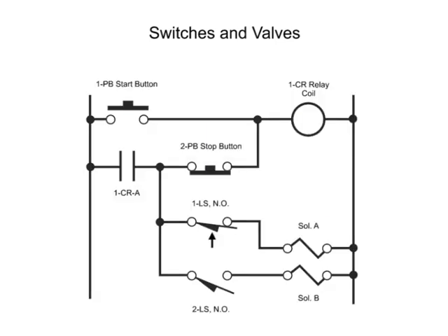For example, consider the limit switch, which is an electrical switch operated by the motion of a machine or presence of an object. In this circuit, there are two limit switches. Limit switch 1LS is a normally open switch. The arrow shown next to the switch indicates that the limit switch is normally opened, but is held closed prior to the start of the cycle.